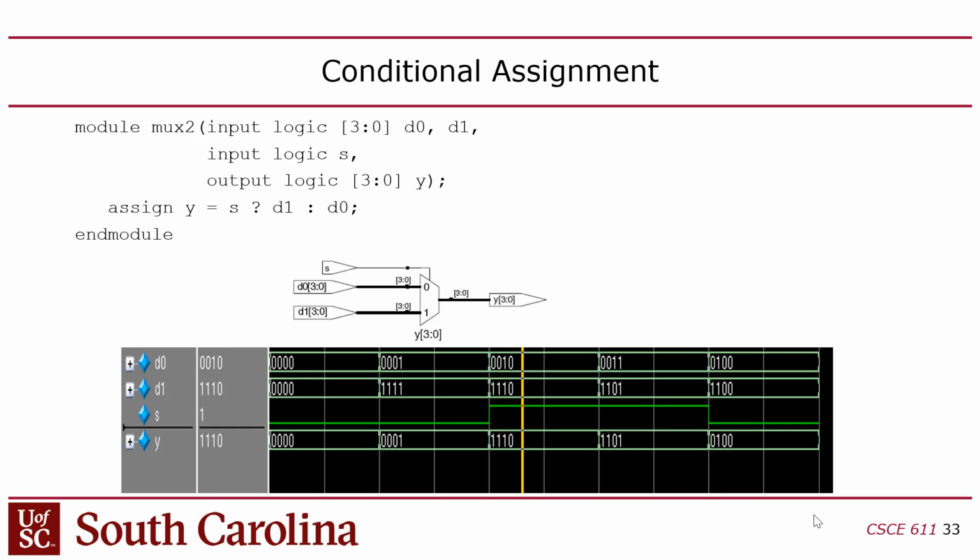But in Verilog, it's very common because this creates a multiplexer in the hardware. In this case, I have assign Y equals, and I check S, which is the condition. This condition is going to be the select input on my mux, and the two values on either side of that colon are going to be the inputs. The only thing that's confusing here is that I didn't say S equals 0 question mark.